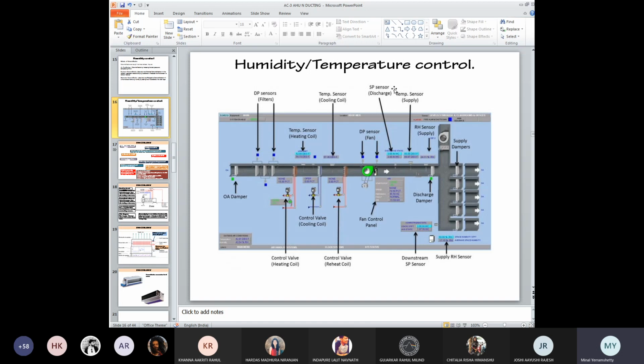If the temperature is going up, the compressor will increase the speed so that faster movement of the refrigerant can happen and the heat is taken out faster. So the moment the temperature goes high, suppose the requirement is 4 and it goes to 10, the compressor speed increases. All of this is so finely related with each other.